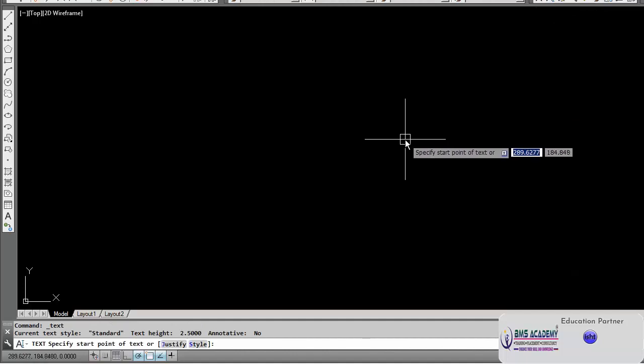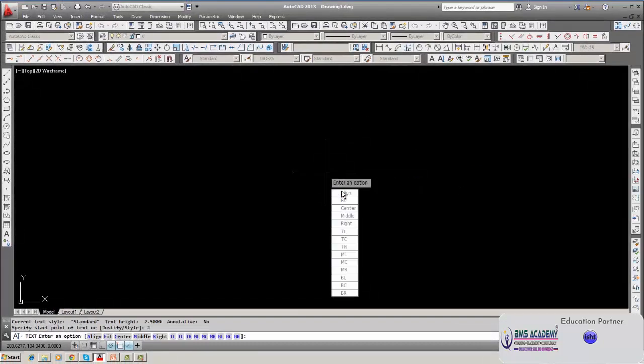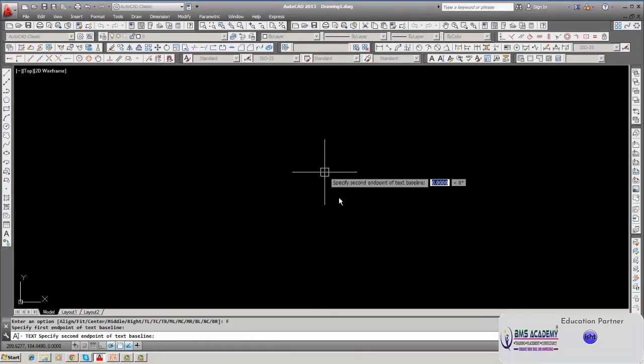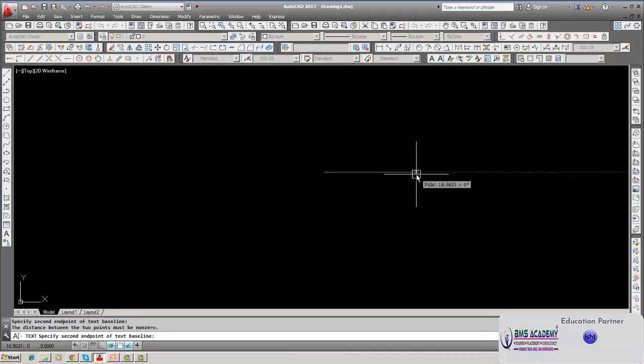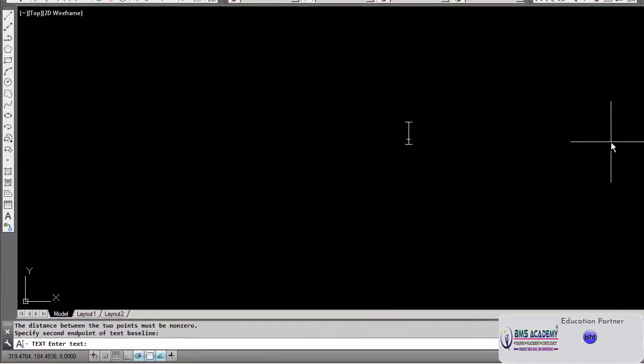Click here. You have to press the right arrow mark, then the down arrow mark. Then a pop-up screen will be there. Press the down arrow mark again, then you will have justification. You click on that. Once again there is a pop-up menu. It will ask you Fit. Then the baseline, suppose I call it 0, and then I will move it, say 15, say approximately 30. So I have moved about 30 mm. Whatever I type here will all be within that.